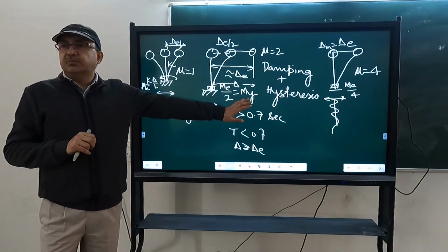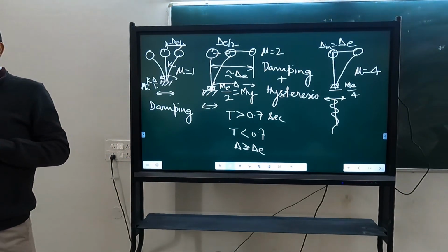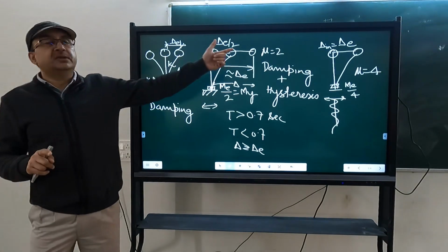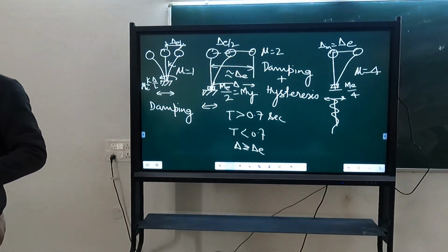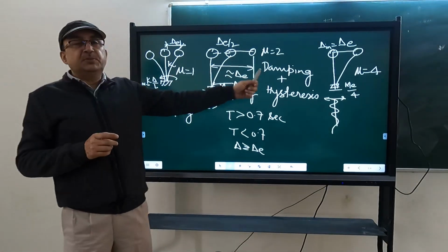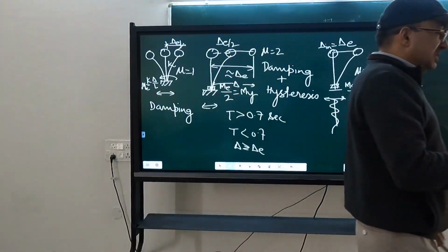So here we are talking about displacement-based design. You think of it like this: earthquake is causing a displacement. It is not causing force. It is causing displacement, and that displacement remains the same. If the structure is strong enough, it can resist that displacement elastically. No hysteresis required. If the structure does not have that much capacity, then it will yield, and then it will dissipate energy through hysteresis, and ductility is required. So that's what displacement-based design is.